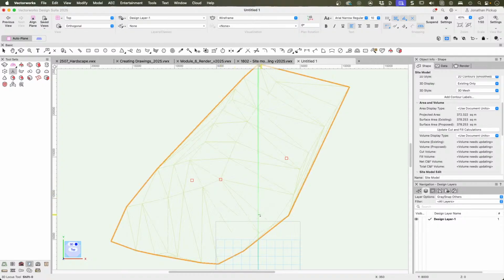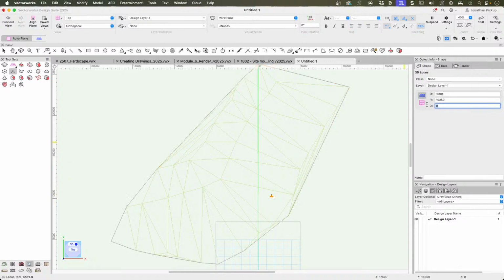So let's say, for example, we know that there's an area through here where the survey didn't measure it properly, but we know it's flat through this area, and so what we really have is some points here. This one should be at 60.1 meters. So let's say we knew that information should be there. If we use our Move by Points tool, and we make some duplicates, we go, okay, so we know that goes this way through here. How do we get this information into our site model? It's going to be the next question.